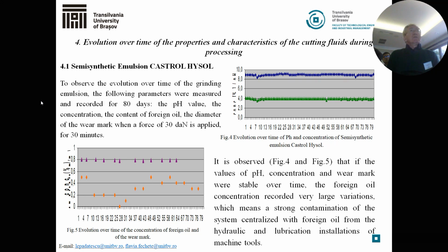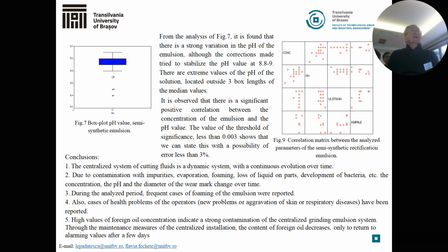It is observed in figures 4 and 5 that while the values of pH, concentration, and wear mark were stable over time, the foreign oil concentration recorded very large variation, which means a strong contamination of the centralized system with foreign oil from the hydraulic and lubrication installation.